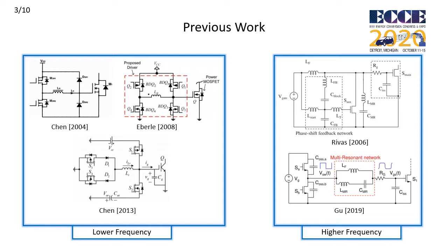Conversely, the two gate drivers on the right fall into the category of what I would call tuned resonant methods, whereby the gate driving voltage waveform is of a fixed frequency and duty cycle as dictated by surrounding component values. This allows one to operate at much higher frequencies, generally speaking, where you are somewhat immune to clock jitter or timing errors because its operation is somewhat automatic.